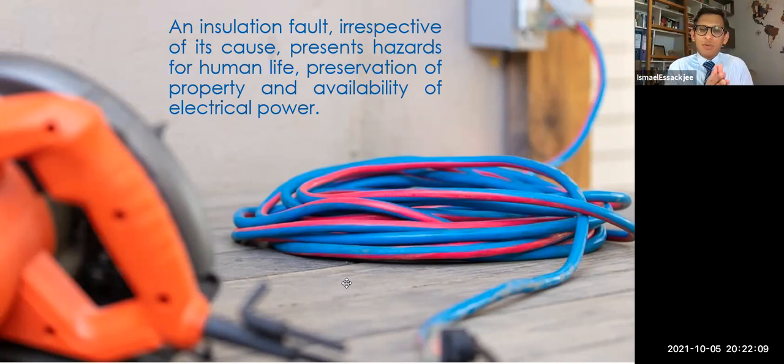We are relating that to IoT, but since we are discussing it, it is a safety precaution. When you connect your cables to equipment working on 230 volts, a higher voltage than you are used to in your project or a small IoT device, you need to be aware that the cables you use should be safe, with proper insulation and so on. Otherwise it can cause harm to you, to animals as well, and to the building and infrastructure you are working in, whether in the lab, at home, or in your small lab at home.